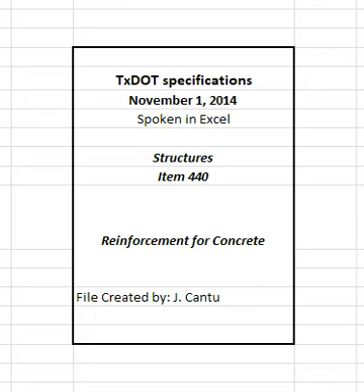3.6 Handling, placing, and repairing epoxy-coated reinforcing steel. 3.6.1 Handling. Provide systems for handling coated reinforcing steel with padded contact areas. Pad bundling bands or use suitable banding to prevent damage to the coating. Lift bundles of coated reinforcement with a strong back, spreader bar, multiple supports, or a platform bridge. Transport the bundled reinforcement carefully, and store it on protective cribbing. Do not drop or drag the coated reinforcement.